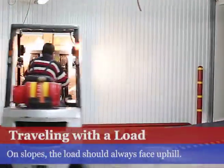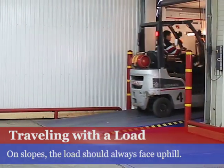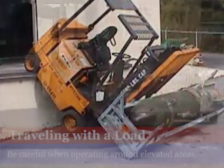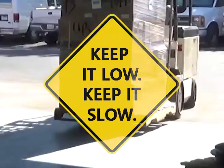Always travel with the load uphill. Never turn, or drive sideways on an incline. Be extra careful when approaching edges of elevated areas, such as loading docks. Always remember, when traveling with a load, keep it low, and keep it slow.